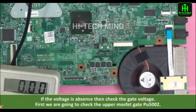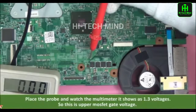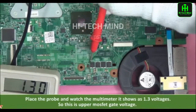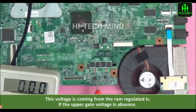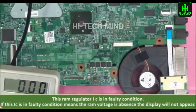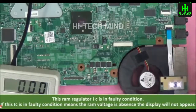First we are going to check the upper MOSFET gate PU5002. Place the probe and watch the multimeter. It shows 1.3 voltage. So this is the upper MOSFET gate voltage. This voltage is coming from the RAM regulator IC. If the upper gate voltage is absent, this RAM regulator IC is in faulty condition. If this IC is faulty, the RAM regulator voltage is absent. The display will not appear.